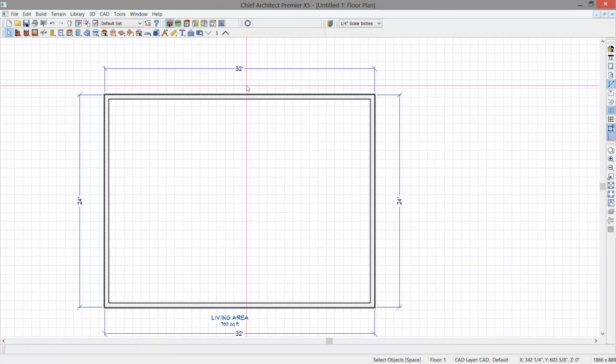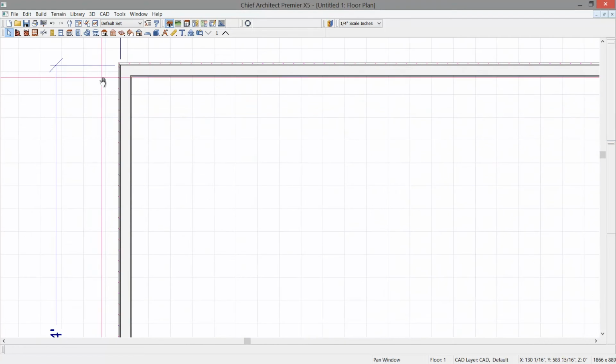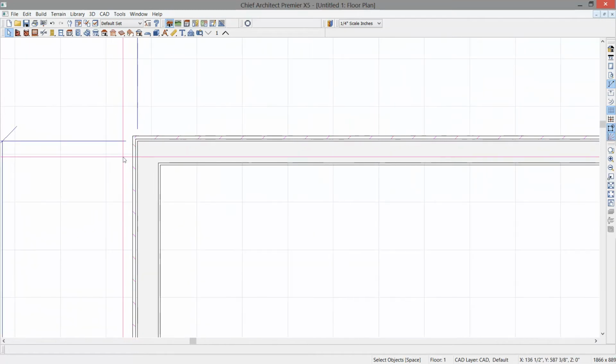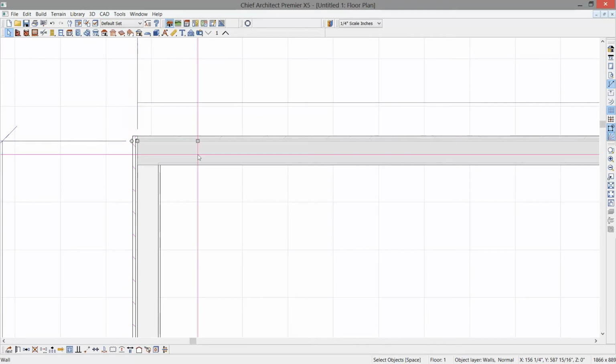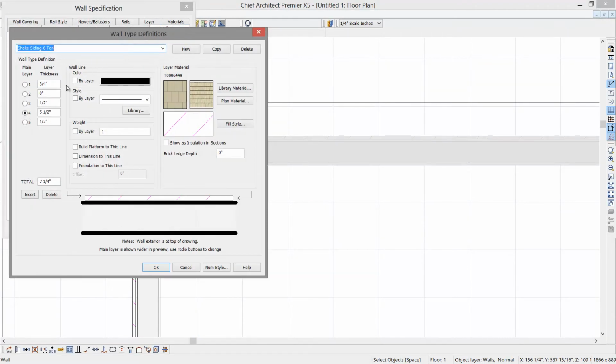Once we've got that set up, if you're a kitchen and bath designer, let's go ahead and zoom in here. You'll notice that my dimension is actually going to the outside of this wall. And in Chief Architect, our walls are actually composed of different layers. Let's explore this wall just for a minute. In this wall type, you'll notice that it actually has 6 different layers here. Sheetrock, siding, the sheathing, and when I do a materials list, all of these components will show up.